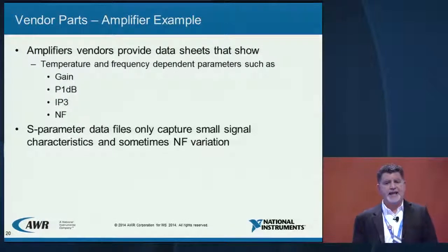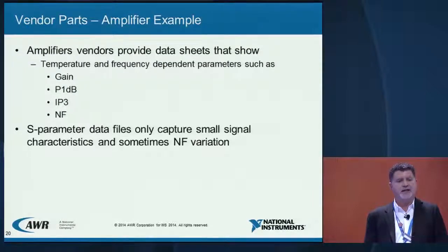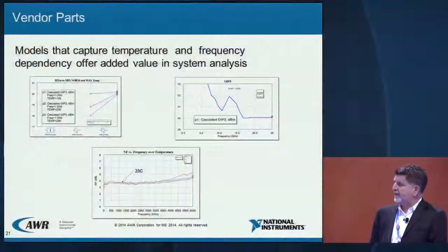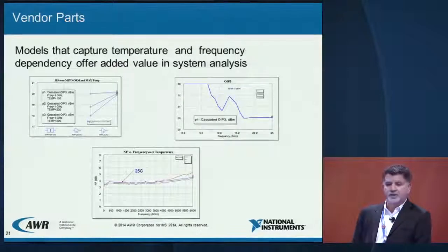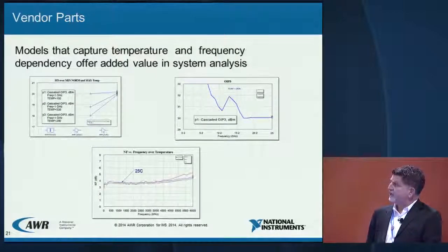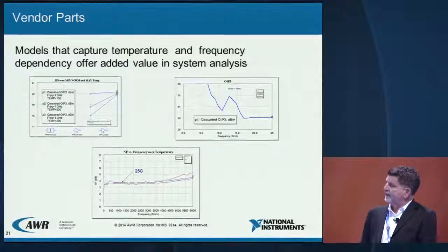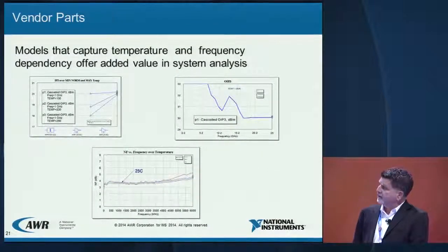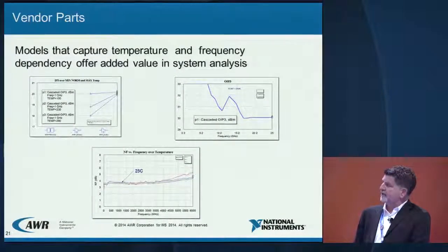We can account for gain, P1 dB, and noise figure along with the frequency dependency of these parameters. Some of the key measurements that you can make are frequency, temperature variation, and noise figure. Here we're looking at frequency versus noise figure at one temperature, and then different frequencies and different temperatures, available gain, with slight discrepancies in the outermost available gain.